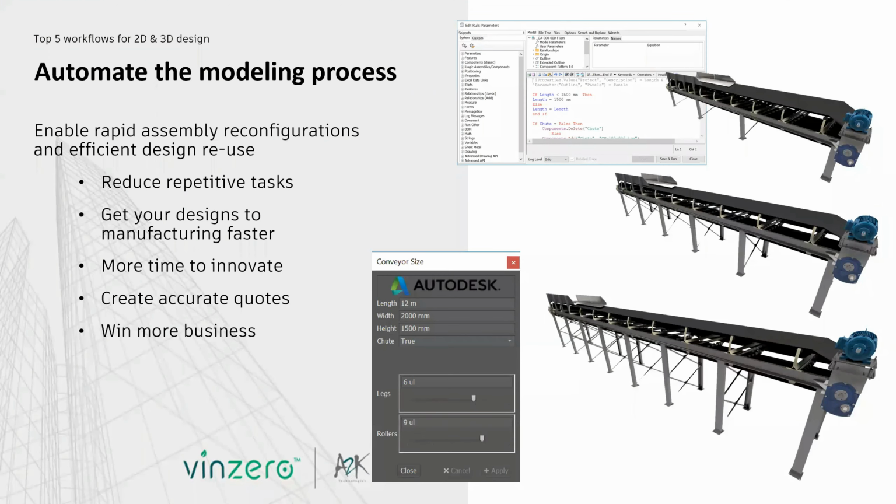Now, for those of you that have been using Inventor for some time, you may have come across the iLogic scenario where we can create rule-driven assemblies. And again, this is another extremely powerful part of Inventor that we don't have time to go into today, but maybe for another webinar another day, where we can use iLogic rules, basically like Visual Basic or programming code, to create variation within our assembly. So we don't have to create a conveyor that's 3 meters, 6 meters, and 12 meters. We can drive that particular rule and work with that.